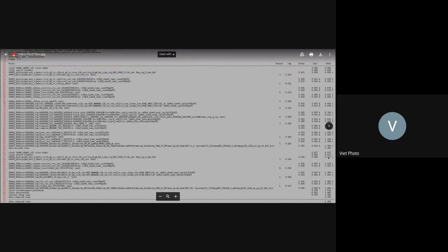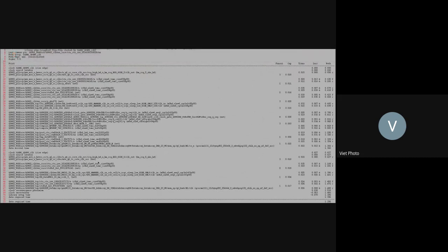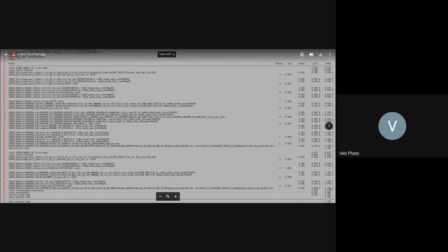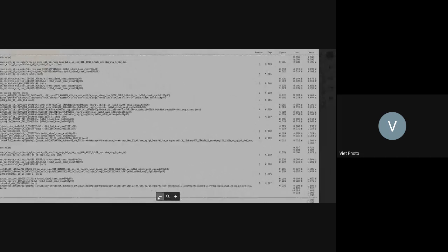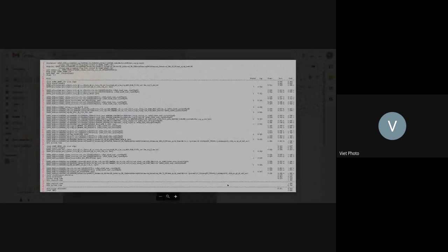So you start with 627 picosecond, and then here they will calculate the clock path again until the end, going into the clock pin here. So the clock arrival in here is 148 picosecond. Hold on. Okay. So we have 148 picosecond.